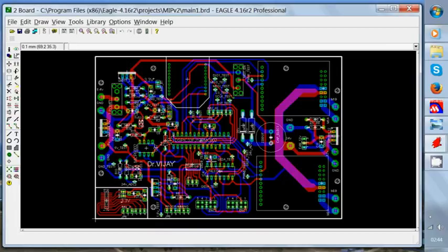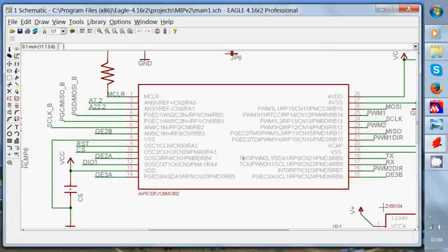So depending on optimizing the length of travel or to avoid the jump of layers of the PCB, some amount of flexibility exists because of mapping internal peripherals of the DSPIC to various remappable pins.